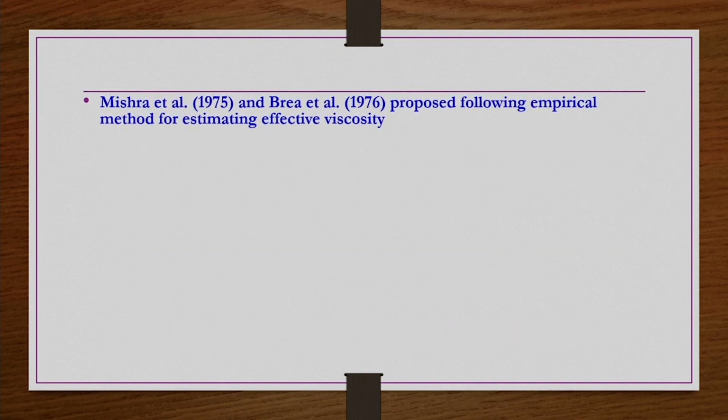So, what we see in a few literatures: Mishra et al. and Bray et al. proposed the following empirical method for estimating the effective viscosity for a fluid flowing through packed beds. That viscosity is given by this one. This is for the case of power law fluids.